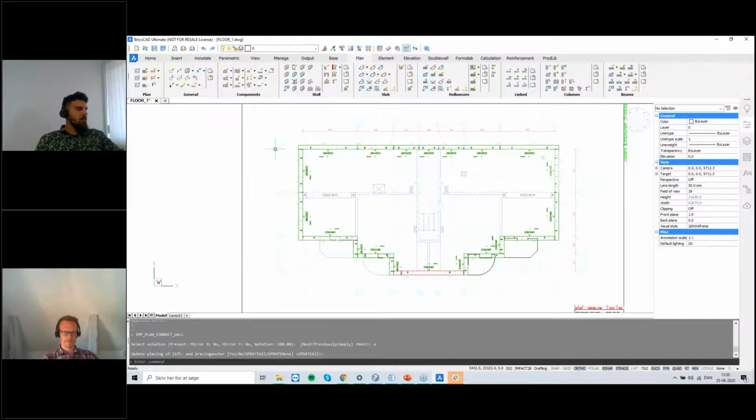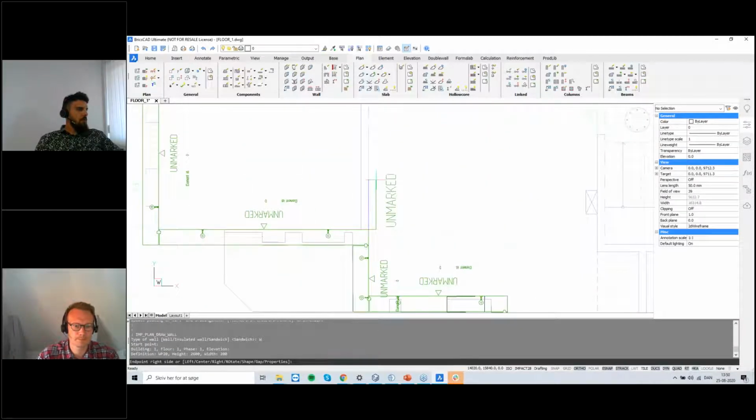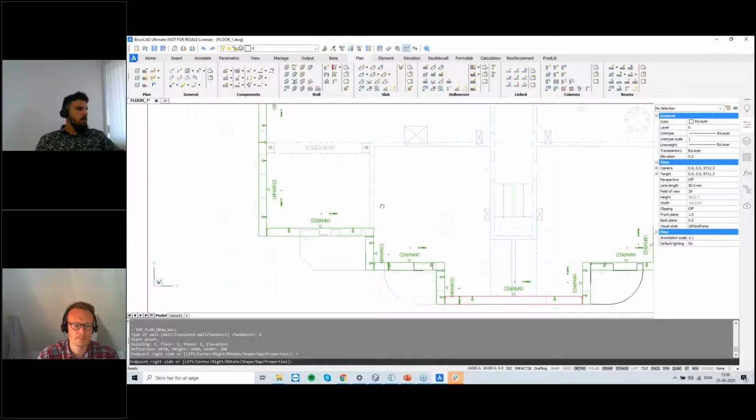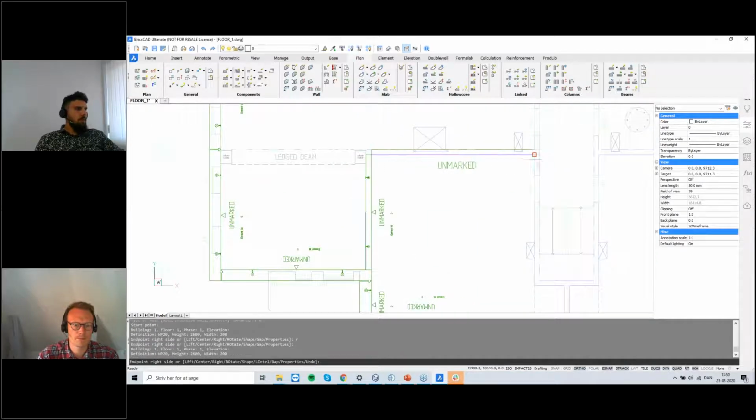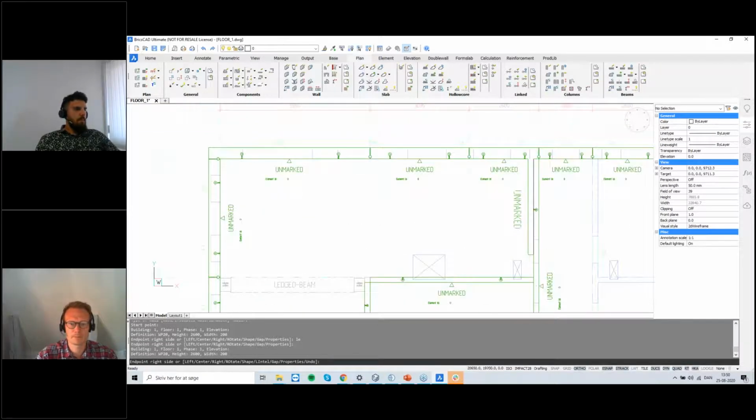But before I add custom materials, because I want to show you something very cool, I will start and draw my solid walls, my walls around here. The principle is the same. We draw the walls, select my walls, start drawing the walls from here. I will go and say right. You see the manipulation of this. Then I press enter 3 times: 1 to close, 1 to open the command again, and 1 to start drawing again. So I will press left and draw the wall all the way up.